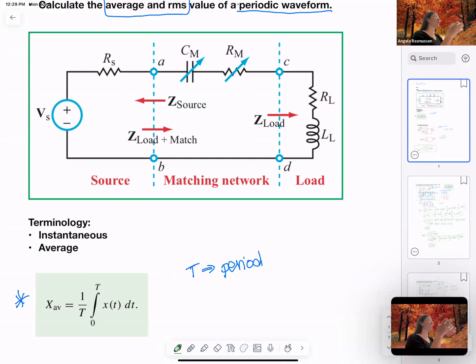So we need to know what values those matching networks are. So now we have what's called complex power, in that we match them based on maximum power output. And so with the power, you're going to have real components, which is resistors. That one we've already known, but now we have time-dependent elements in there of capacitors and inductors. That adds in a complex matching part to it that we also have to match in the power domain or power area. And so that's why we're looking at these terms, to figure out what this matching network is going to look like.